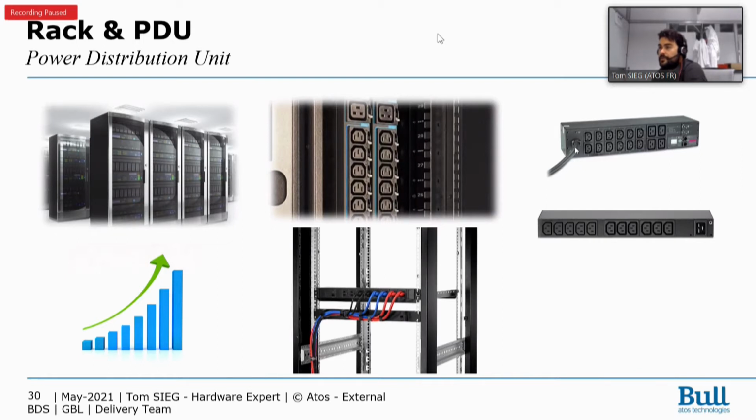This power inlet has a maximum capacity on the data center infrastructure. Generally you will have 16 amps, 32 amps, or 64 amps. That is the standard, and the more common power capacity you will find for the inlet itself.